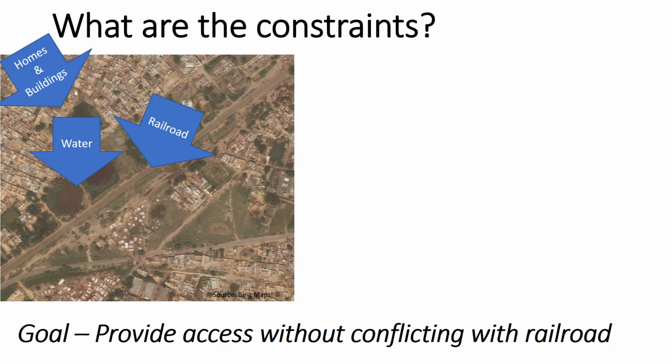And so the main thing with the railroad is providing enough clearance. Either you can also go below ground to provide this, or above the ground. Typically, in a lot of cases, you're going to see that going above the railroad is the more feasible option. And then, of course, the roads in the area, the full system, and in particular the road shown here, which is going to be connected to.